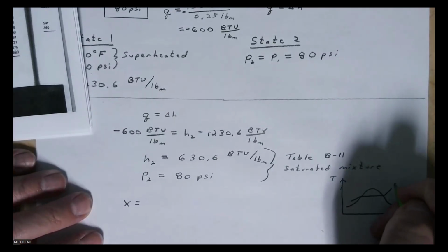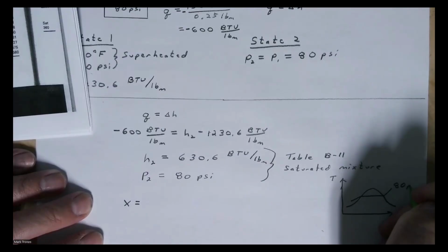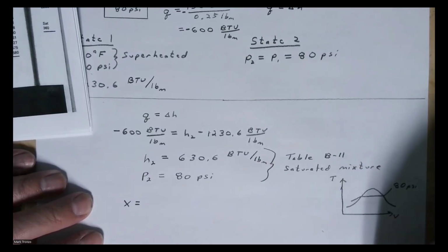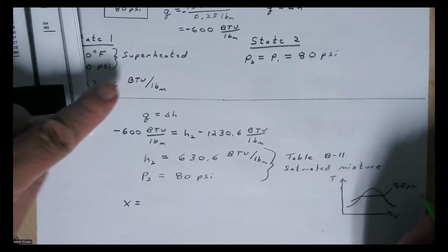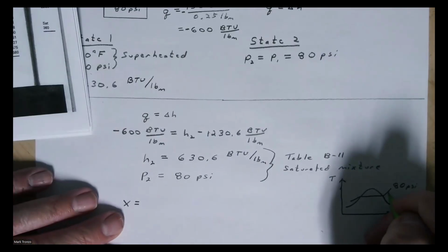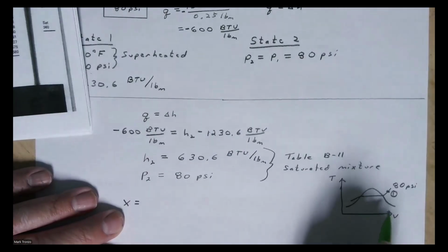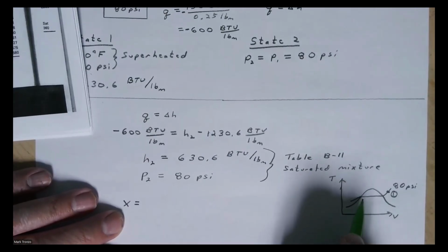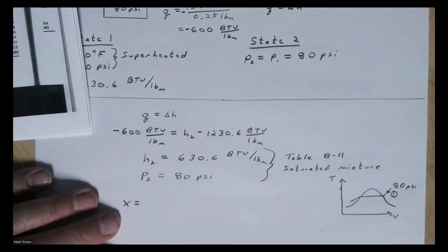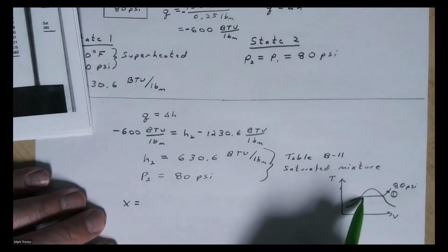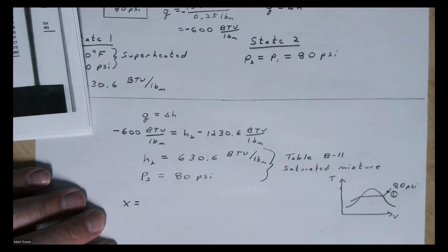We're at 80 psi here. And remember, we started up here at superheated, so we were maybe up here somewhere at state one, superheated. And now we know that we're somewhere in here for state two, not sure yet exactly, but we know we're somewhere inside that region.